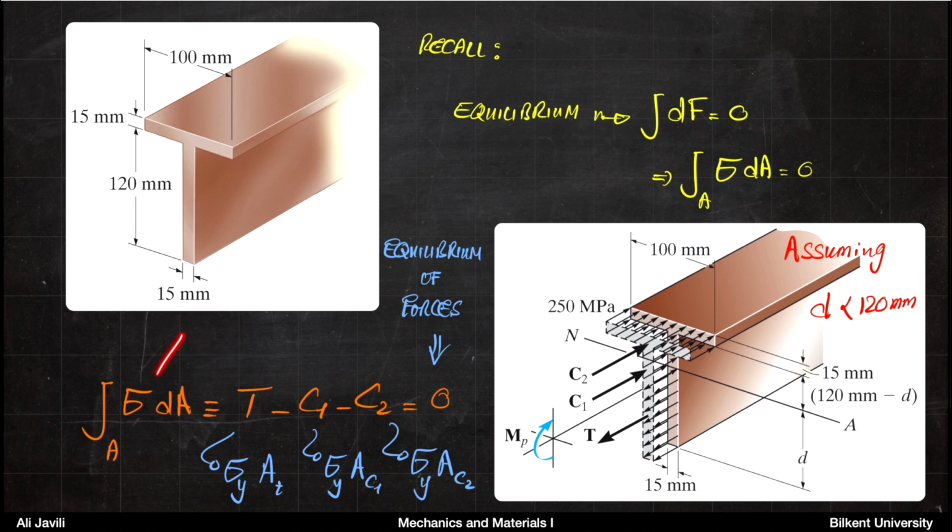that when you want to insert stresses here, the stresses do not have a linear distribution. They are all sigma_y. They are all yield stress. Because for instance, we are thinking of a case where you have fully compressive stresses above a neutral axis. So assuming that this is your neutral axis, we are assuming that everywhere above the neutral axis is fully compressive and at the yield stress, and then everywhere below it is tensile.